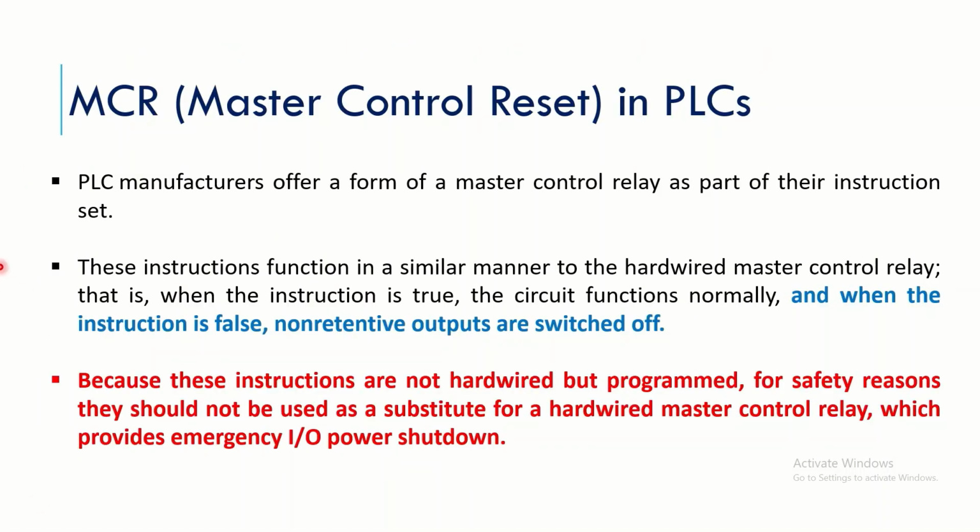Okay. Now you see that PLC manufacturers actually offer a particular form of master control relay in their instruction set. Remember, the instruction functions as a hardwired master control relay. When the MCR instruction is true, the circuit functions normally. And when this is false, remember, all non-retentive outputs are switched off.